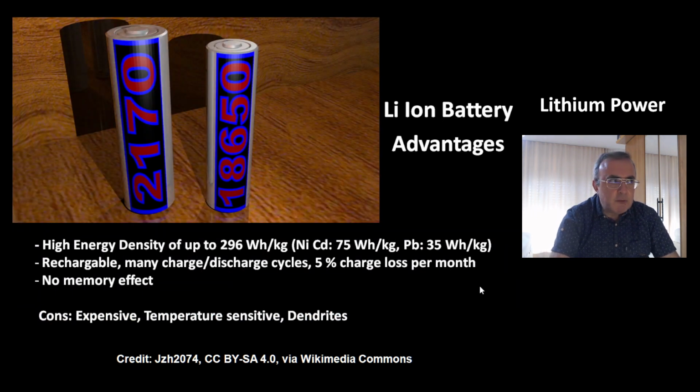Lithium-ion battery has several advantages, one of which is its high energy density of up to 296 watt-hours per kilogram. It is rechargeable many times, and it has very little loss per month and no memory effect. Disadvantages are it is expensive, temperature sensitive, and the formation of dendrites.